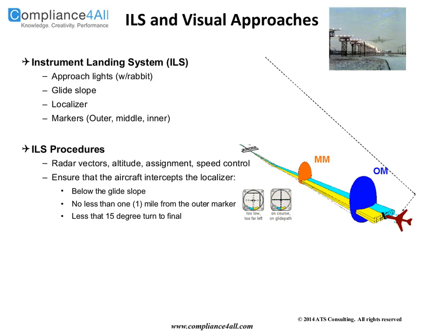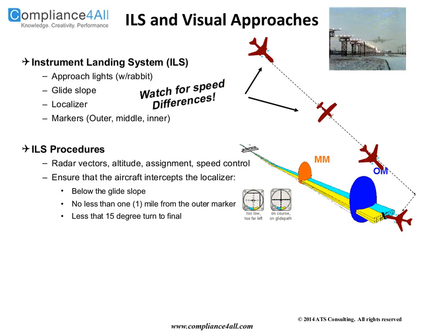This is an example of why I'm talking about things you possibly don't know. Back when I first went up into the R&D part of FAA, there was a system then that was trying to replace and upgrade the ILS system. It's called microwave landing. And the technology was phenomenal. Okay, it was really, really good, and it allowed for curved approaches from all over the place, without being dependent upon this single beam, the localizer and the glide slope. So it had all kinds of huge advances in technology and capabilities that never went anywhere. And the reason for that is that they made the simplifying assumption and didn't consider all these other airplanes, and the fact that they are of different capabilities, different speeds, different characteristics.